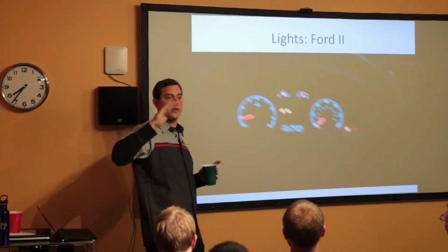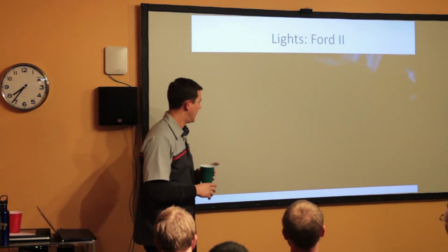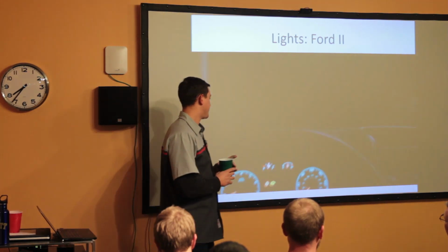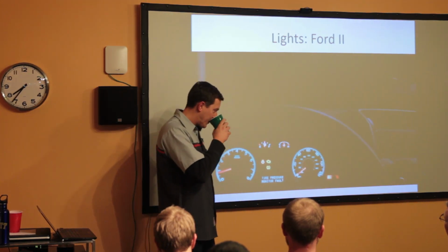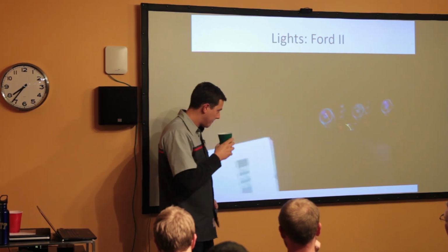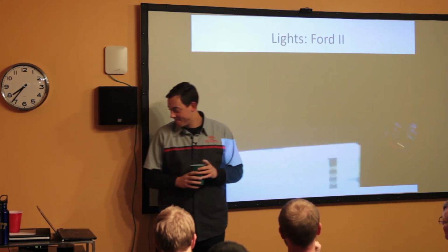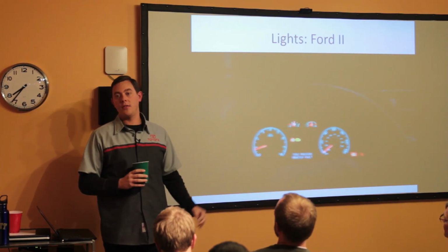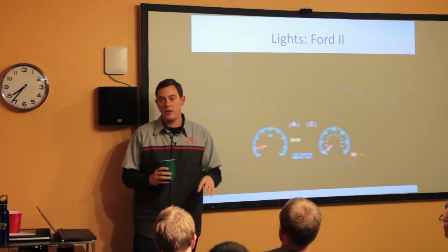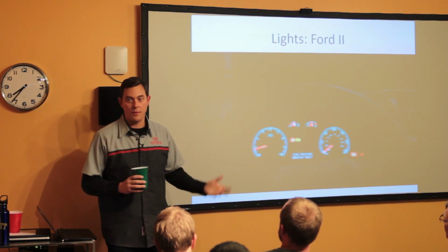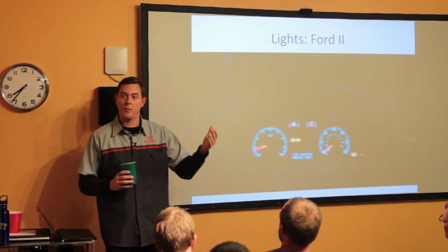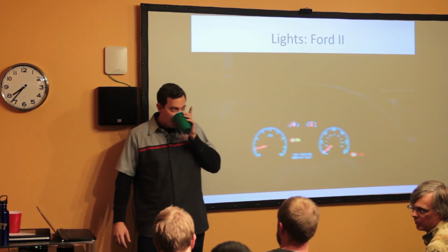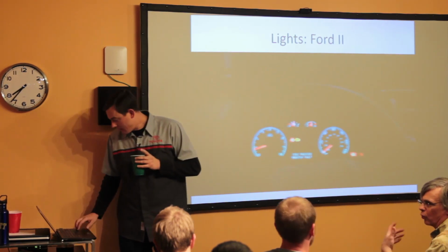Yeah, the tail lights, there's no brake lights. The solenoid won't unlock. No matter what you do, the brakes work, but the brake lights don't work. Then you can't get out of park. You're stuck in park. Is my DOS in the CAN bus? No, you're just putting the one ECU into a reprogramming mode. And from that, it kind of shuts everything down and is waiting for firmware. But when you do a reprogramming session, the very first thing you should do is tell everybody to shut off. Yeah, but that's before you do the reprogramming.